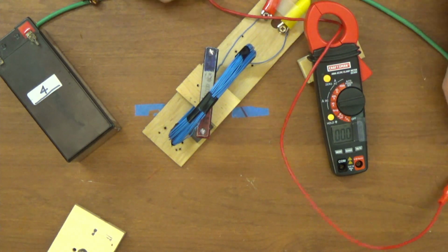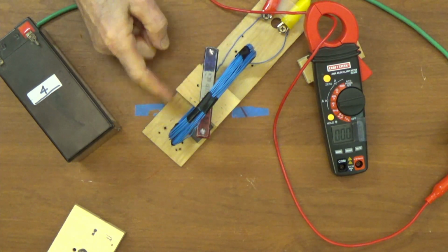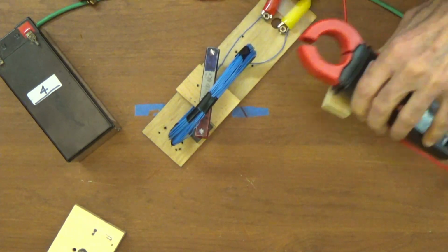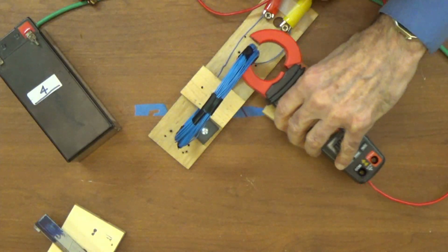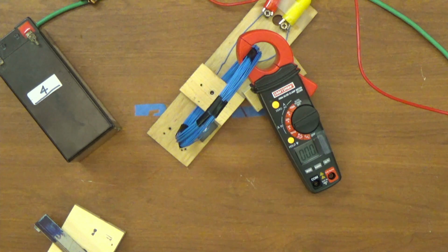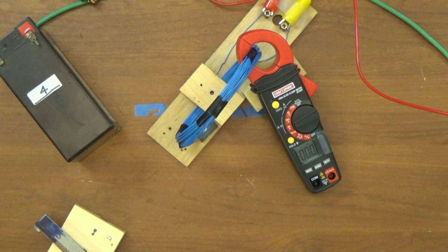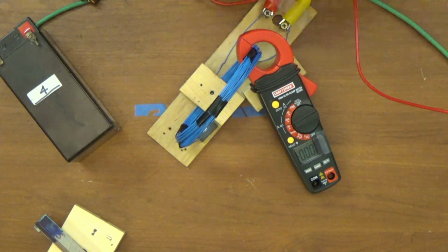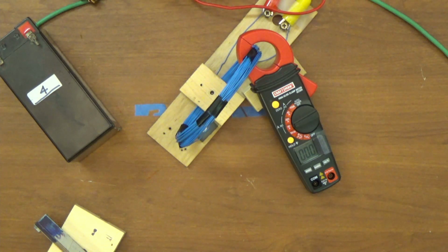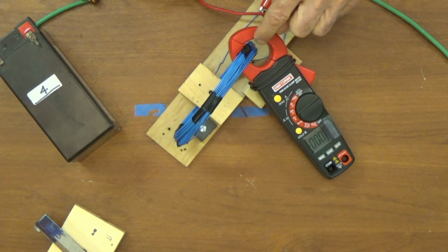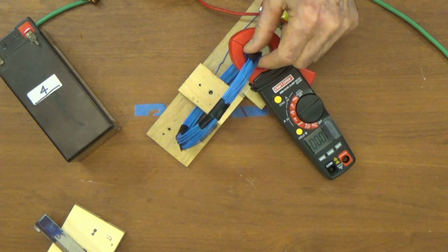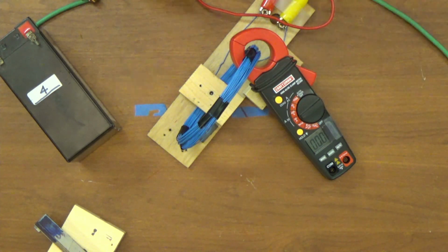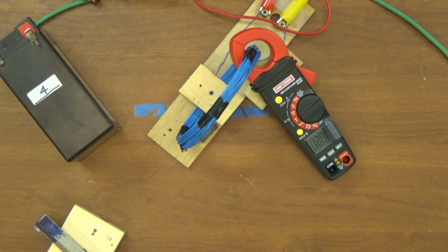Well, those 1.7 amps are going around and around and around 50 times. Let's take a look at what that means. And get the magnet out again. Is that visible? We're going to do the same thing now, but we're going to measure what's going through here. And this ammeter doesn't know that there are 50 turns. It just knows all of the electrons that are going through there. So there's 50 times 1.7 amps going through there.